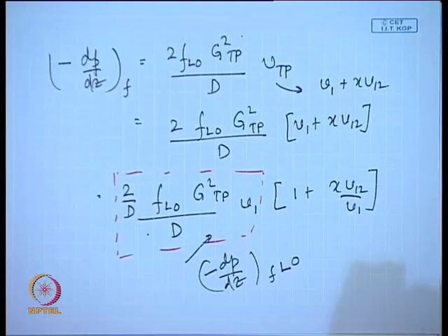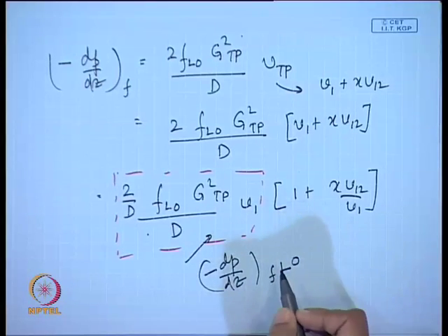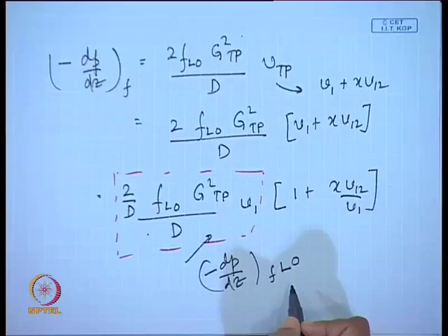only in the pipe. So, how does it simplify the situation? In that case, we can just take liquid at the total mixture flow rate and we can allow it to flow through the same pipe. Under that circumstance, finding out the pressure drop or the pressure gradient becomes very easy. Yes or no?